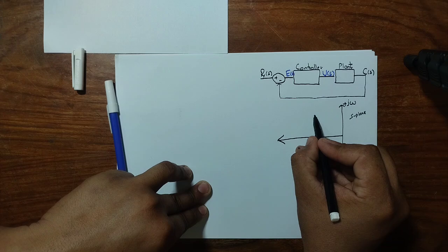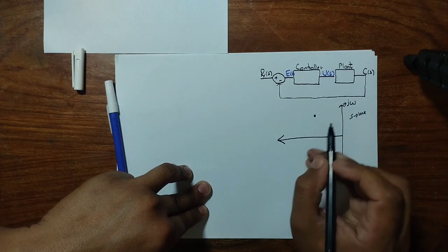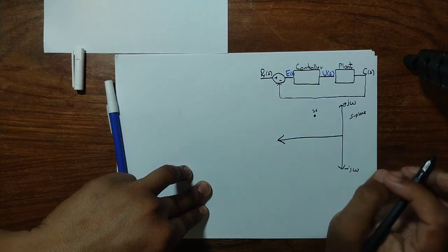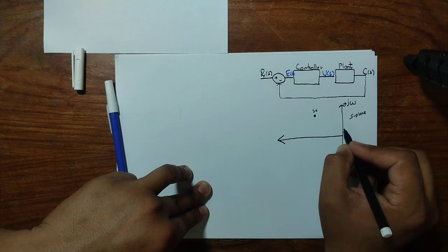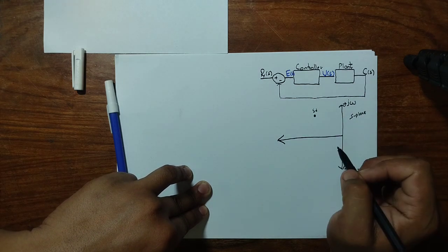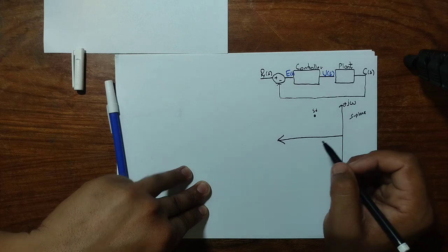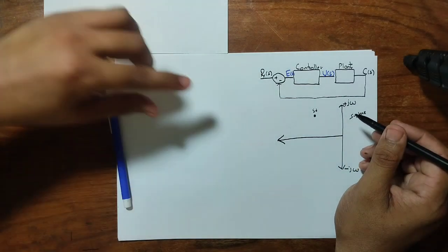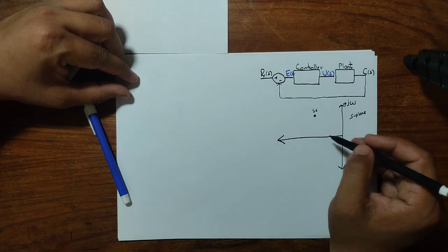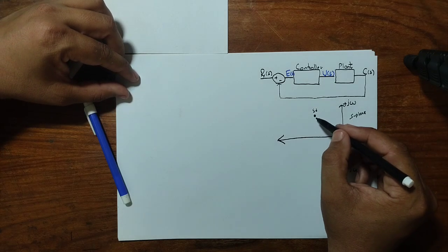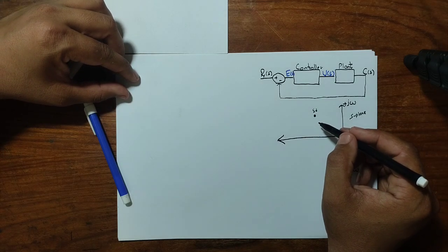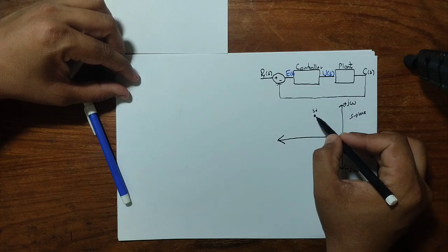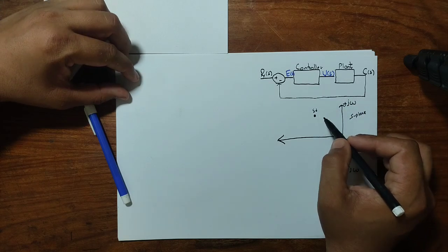Let's assume that we are trying to obtain this operating point, that is S desired. Right. So to meet this operating point from our system, we will use the control system, and we will try different kinds of controllers like proportional plus integral and proportional plus derivative controllers, so that our root locus should pass through this point. And if our root locus passes through this point by adjusting the gain of the controller, then we can achieve this point as a desired point.